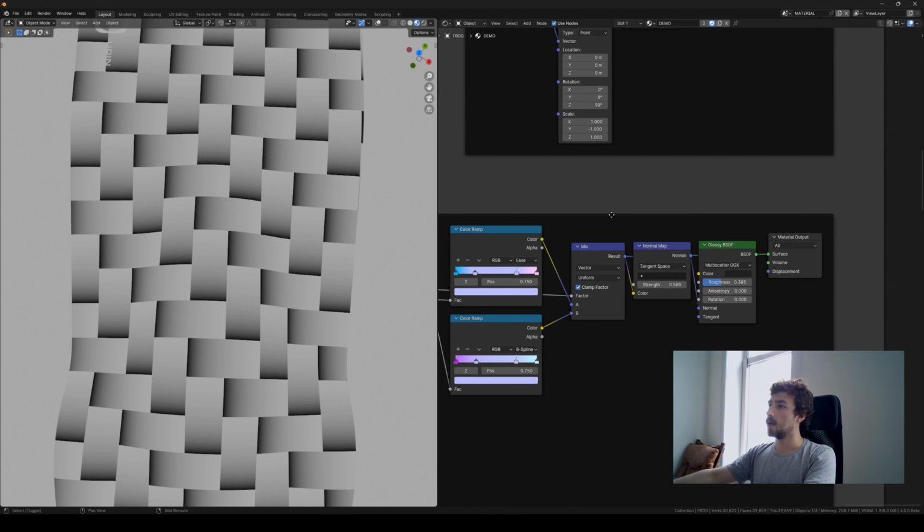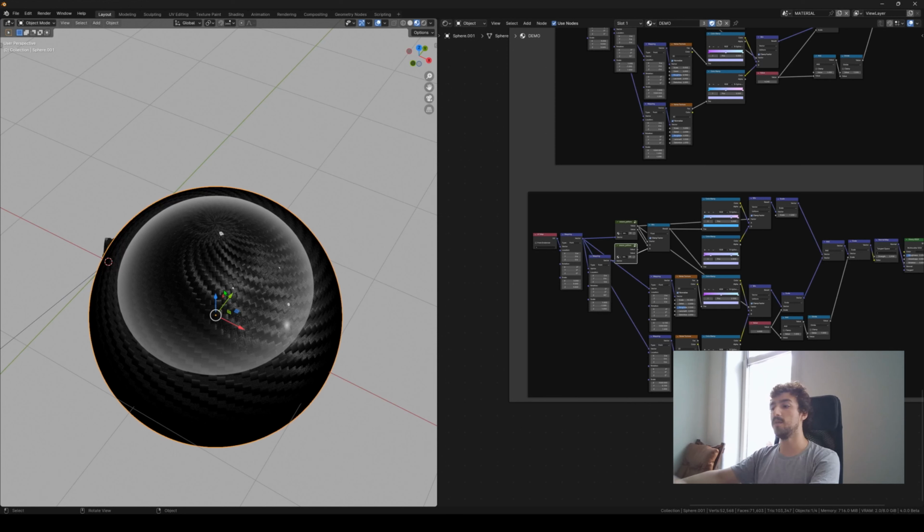doing the UVs ourselves. And so we will see a method which is called the triplanar, where you just base it on your object, but you don't need to. We will recreate the UVs basically, whatever the object. So if I go here, the goal will be to create exactly this. So we want to just project from each main axis. So the Z, the X, and the Y.